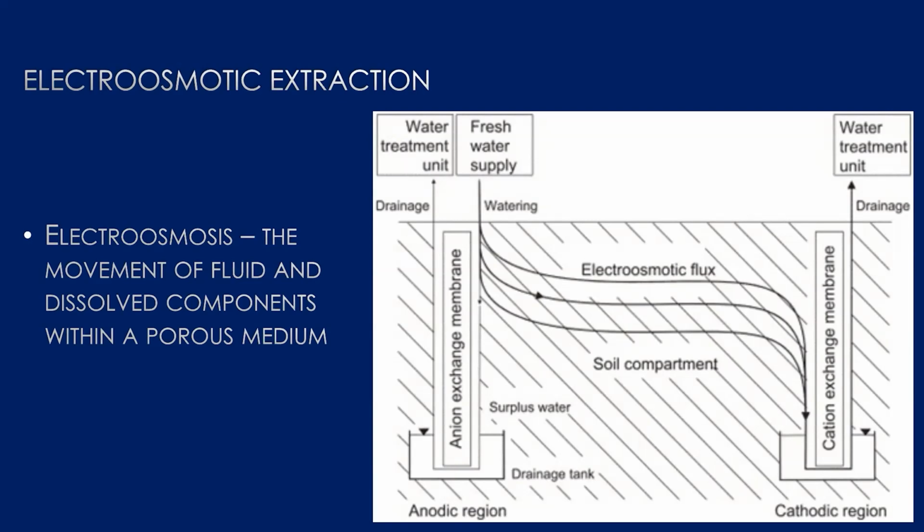The reason why the water supply is added to the well containing the anode specifically is because most soil particles are negatively charged, which attracts cations into the soil to line the boundary of the porous medium. Water molecules then align around the cations, with any remaining water molecules completing the boundary layer around the cations and the negatively charged soil surface. Now, the water molecules aligned with the cations are on the outside of the medium and are positively charged due to their close proximity to the dissolved cations.